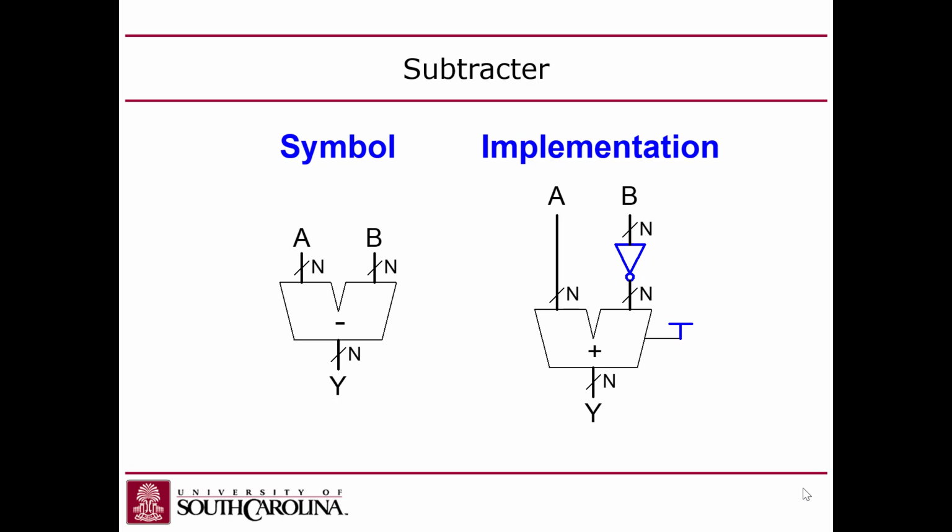Make sense? You can regroup these because addition is associative. But actually, you're not really even doing that technically, because it's not like you're adding A and not B and then adding 1. The adding 1 is part of the adder itself, so there's not really any kind of ordering there. Does that make sense? This is something we actually did in your CPU design, as part of the ALU code that we gave you.